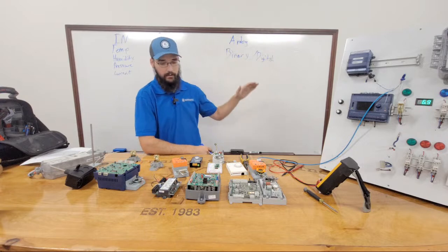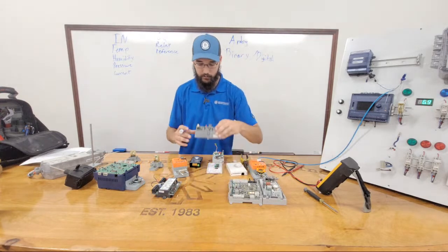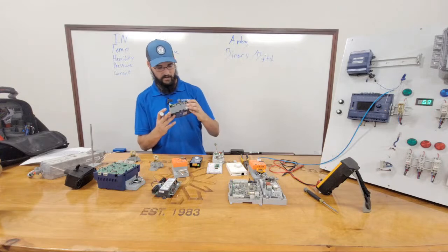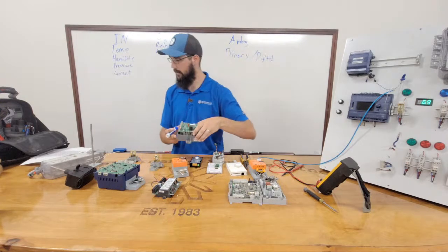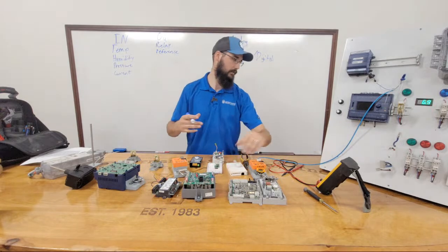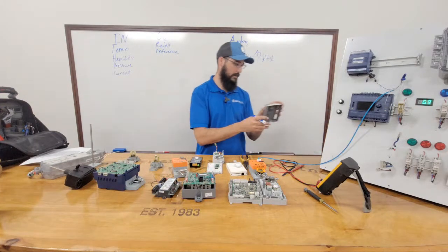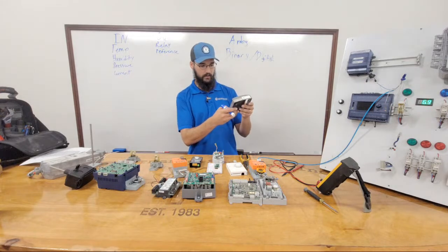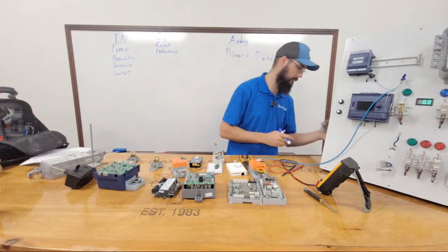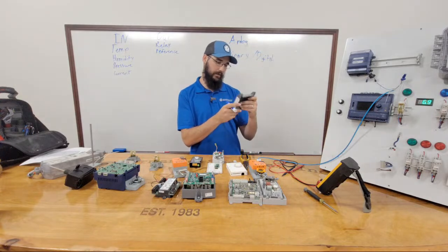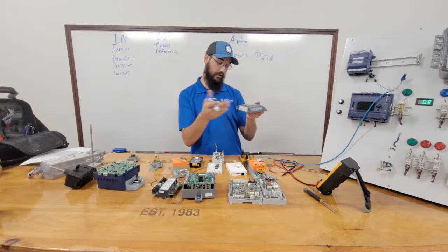Binary, digital, same thing. Usually referenced as a B or a D, so that is just manufacturer preference. I'm trying to see if JCI specified. I got the cover somewhere else. Right here. How did JCI say it? So JCI says out. Just O. Okay, well that's less helpful. Honeywell references it as a digital.